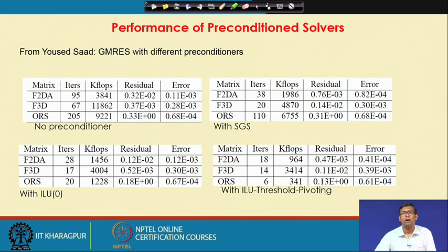So, magnificent improvement in performance can be obtained if preconditioners are applied properly, because the condition number of the solution matrix can be very well adjusted so that it comes very close to 1, and in very few steps we get the right solution. I tried to give you a brief overview of preconditioners, but it actually requires much more discussion.